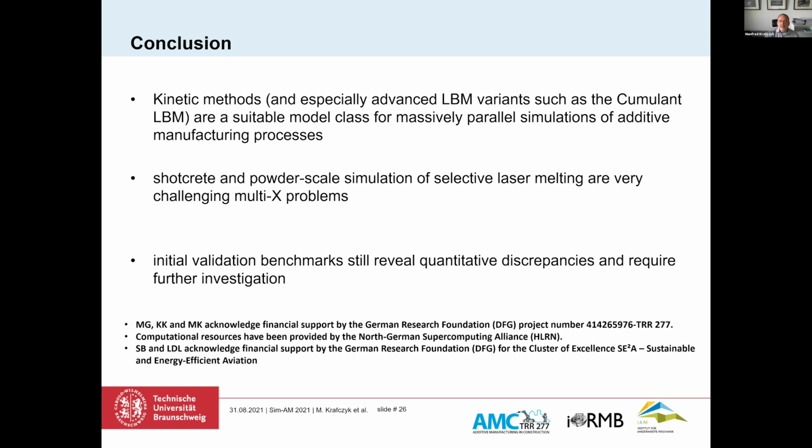So what we model is the laser beam that induces a thermal load, which leads to a melting of the solid, and the molten flow is then solved or described by a Navier-Stokes type solver. What we don't have yet is the transition from the fluid phase to the gas phase.